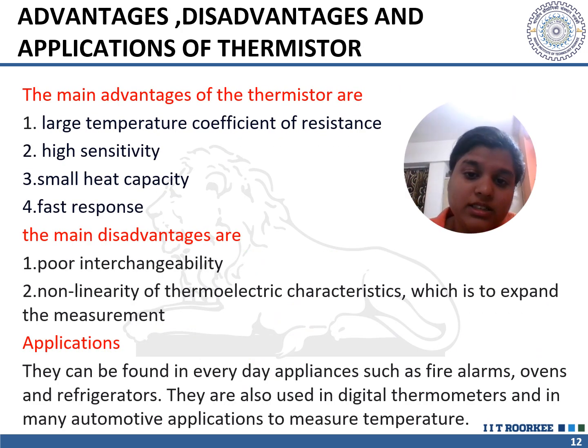Now, advantages, disadvantages, and applications of thermistor. The main advantages of thermistors, I have mentioned a few, but there are many. Large temperature coefficients of resistance is one of the advantages. High sensitivity, small heat capacity, and fast response are also there in thermistor.